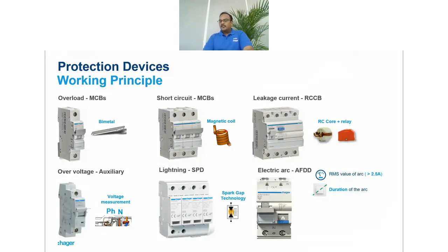So irregularity of the arc, because an arc can happen sometimes, there can be a blank, that can happen again, carbon deposits happen. So all this is being considered. There is a high frequency disturbance sometimes, when the arc is in a bigger cable, we can actually hear the sound, but within the homes and offices, we can't hear the sound, but there is an arc and a very little hissing sound as well, which can be generated. So there is a frequency coming up. A specific arc waveform is monitored by this device.